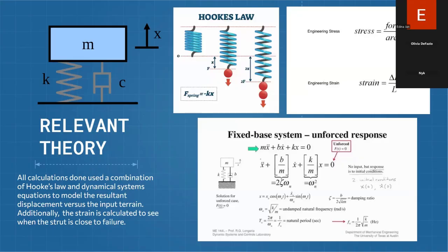So the system that we're using, since it is basically a suspension system, can be modeled as a spring mass damper system, with the mass being the weight of the aircraft, and that's modeled just by using the load frame. We're going to use the force from the load frame to help calculate the K value, the spring constant, for the initial conditions. And we're going to use the initial no load scenario to find the damping coefficient.